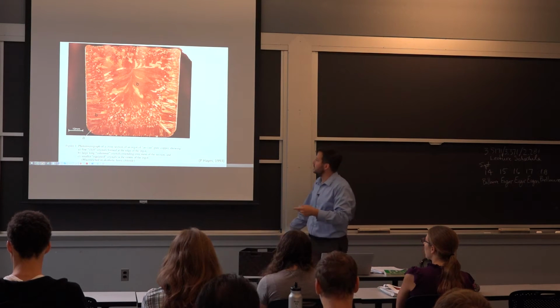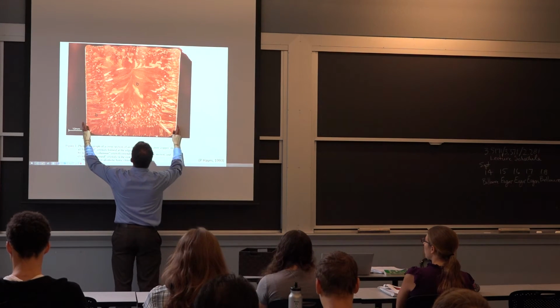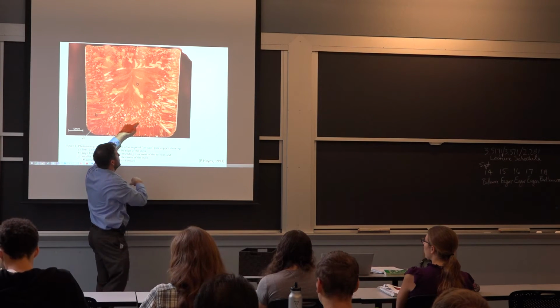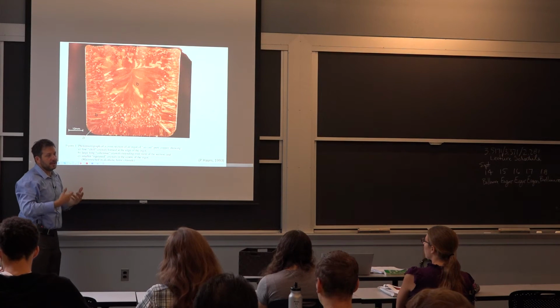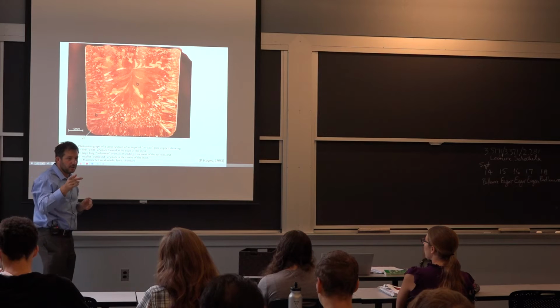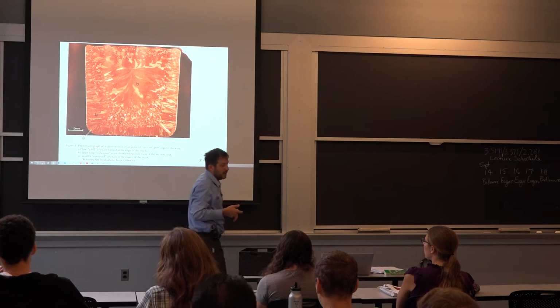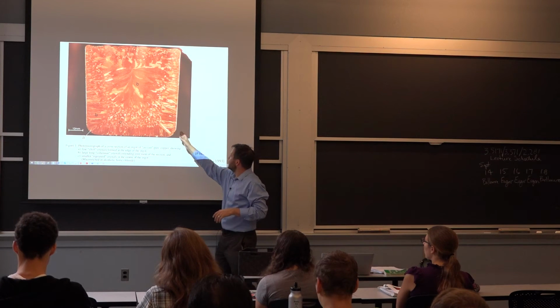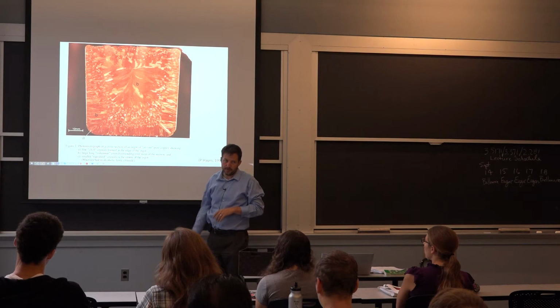And the reason is, instead of being this size, it got deformed and deformed and deformed to a point where all of this has changed significantly, and now it's a lot more homogeneous. The aluminum part will have a little bit of this segregation, where the properties on the surface, where it starts to solidify, are different than in the core.